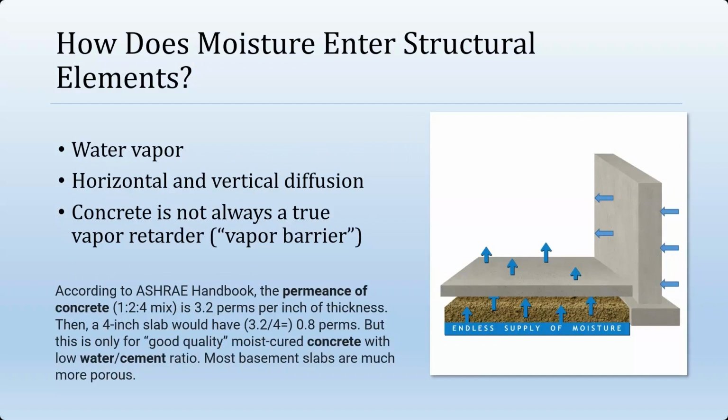Whenever we build below grade structures, we should always consider that the soil should constitute basically a 100% relative humidity moisture source. And if we consider northern areas like Minnesota, if I last recall, has a 96-inch frost depth per the code, which is obviously 8 feet.